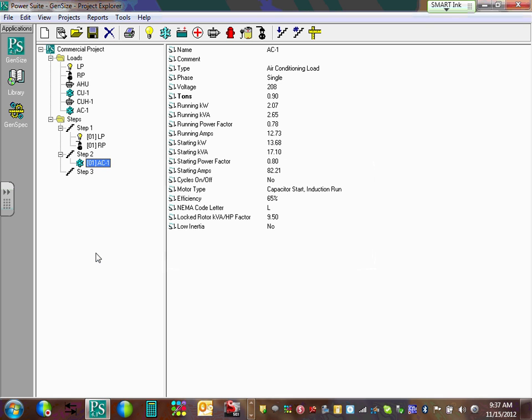This means the auto transfer switch will send a signal to that server, saying hold your horses 10 seconds until the lights and the receptacles come up to speed. Can I have thumbs up, Chad? Good. All right, next. Then you start picking. Which load do you want to start next?